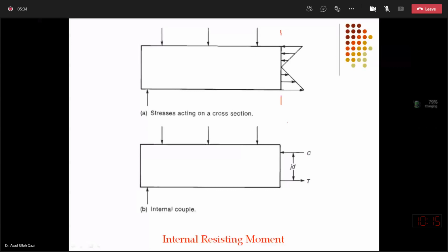then if we apply bending stresses through the application of load on the beam, whether it is the UDL or the point load, at the maximum stressed section, which for a simply supported beam is the midspan, the neutral axis is almost at the mid of the gross depth. Since the material is elastic and the section is uncracked, in tension and compression stress and strain increase linearly.